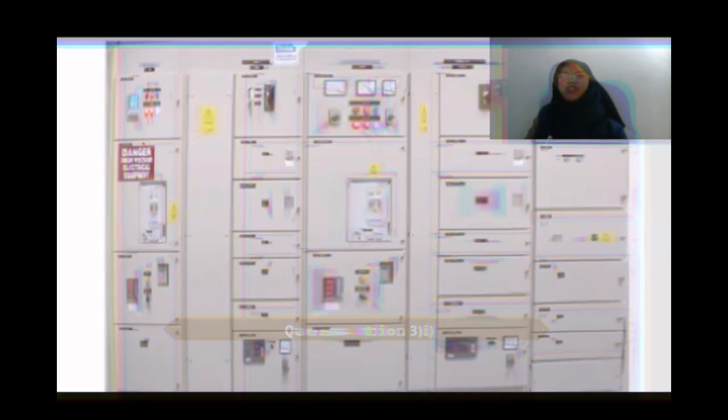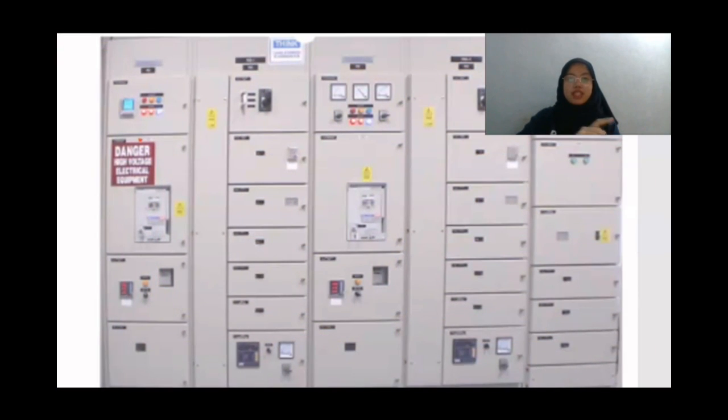Based on this low voltage switchboard, on the left side is the digital meter, and on the right side is the analog meter. It consists of an ammeter, a voltmeter, which have their selector switch to select scale, and a power factor meter. All the meters are to measure voltage, current, and power factor through the switchboard. At the bottom of the meters, there are three indicating lights to monitor and alarm the operation status of this LVSB.